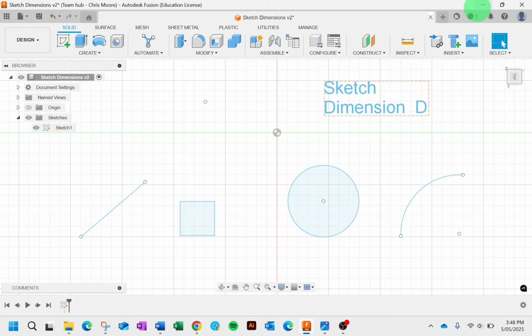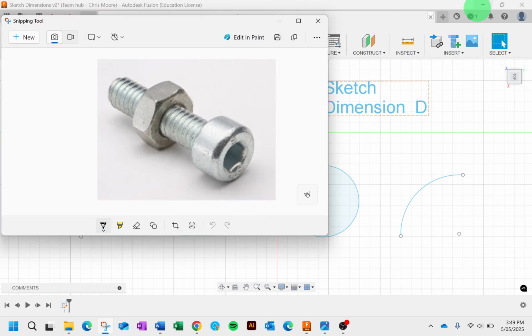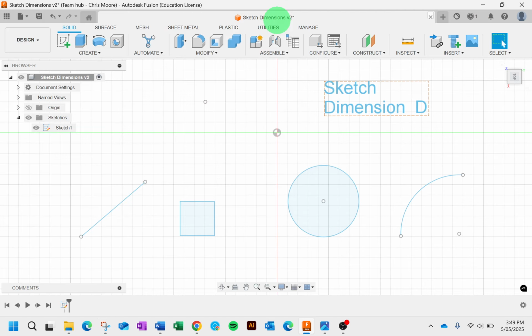Hard materials like plastics or metals need precise tolerance because they do not bend. Components must fit together with just enough clearance. For an example, the nut threading onto a bolt. If it's too tight, it won't actually thread on, and if it's too loose, it's not going to be easily tightened and so therefore lose its function.